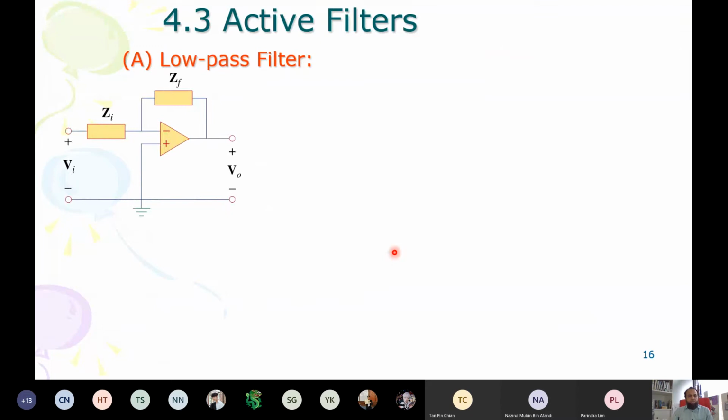You don't need to remember these. If you know, that's good for you for your practice, what type of circuit there is. But basically it's about having the gain. This is the simplest structure. This is the amplifier. Do you guys remember the properties and how to find the voltages for amplifier? Like how do we write the equation, how do we get the transfer function equals ZF upon ZI? Can anyone tell me?